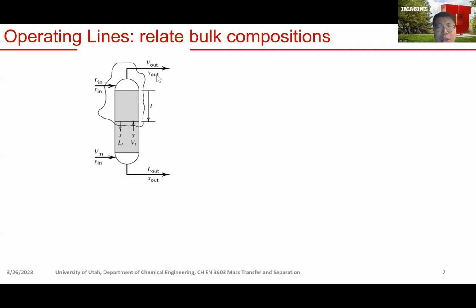Okay, so basically we can write down the mole balance equation for this control volume. Now here, different from the tray tower scenario, in which we use mole ratios, that's capital X and Y, right? We also use the solute-free fluids, that's L prime and V prime. So here we use the mole fraction, right? That's lowercase x and y, and the total fluids, right? That's L and V without prime, right?